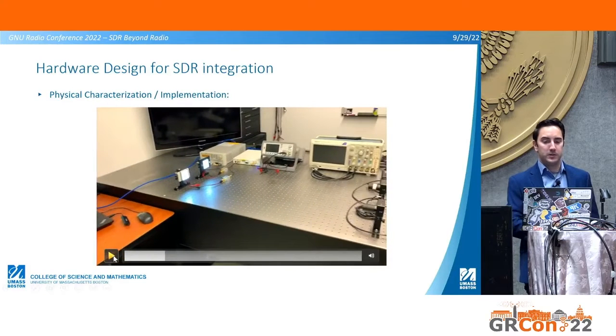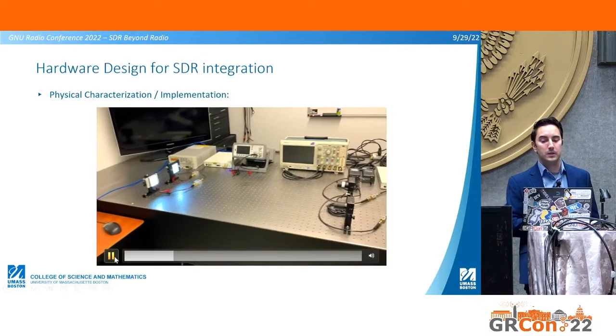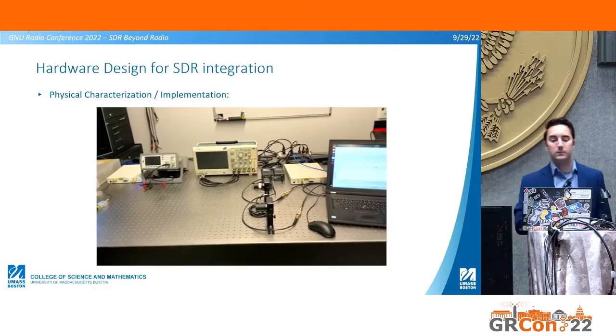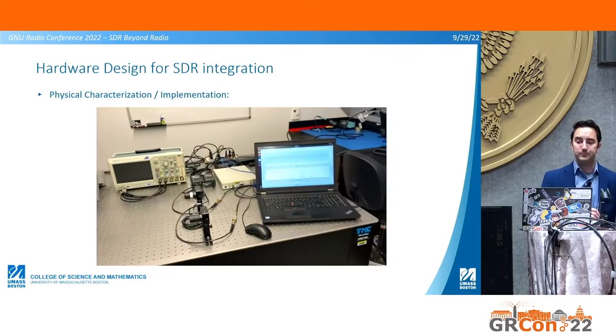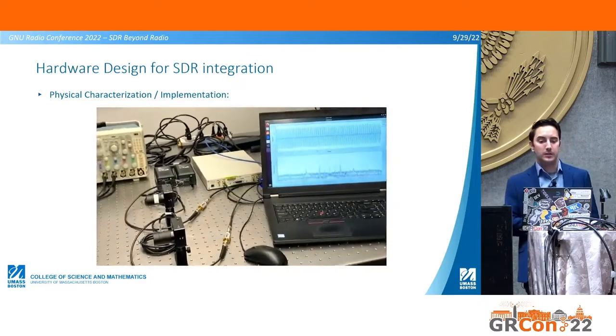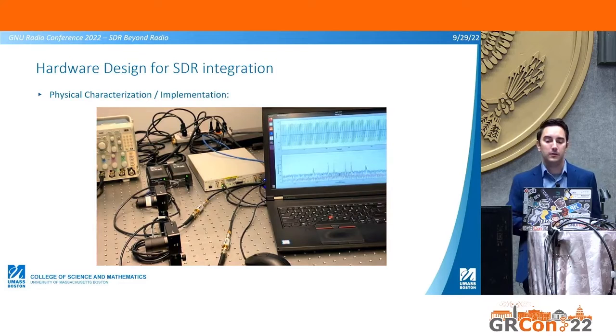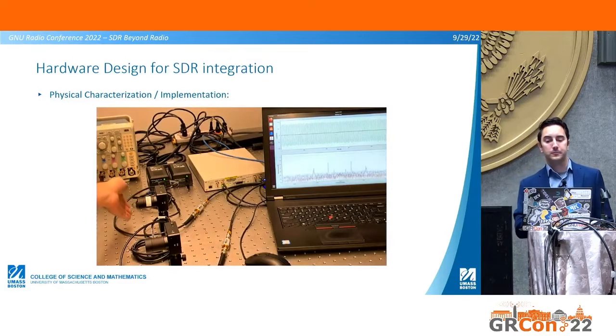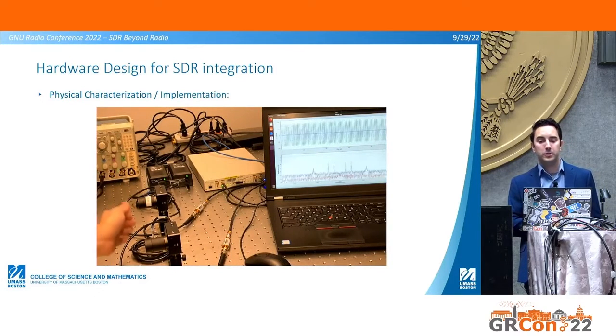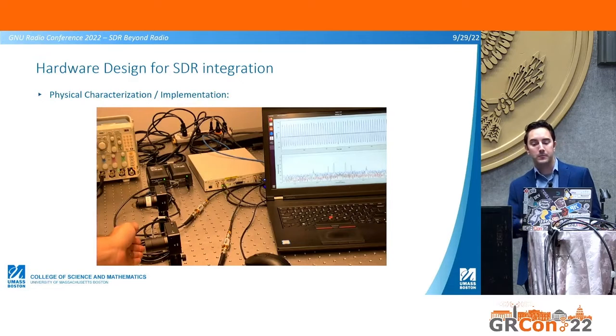So on the transmit side here, we have the USRP passing through two DC bias Ts, RF bias Ts, to bias your signal into the linear range of the LEDs. Both of these little low-cost LED arrays are right now just sending a sinusoidal signal, picked up at the two photosensors at the other end. As we zoom in, you notice that if we block either one of the channels, one channel goes away, and then the other channel goes away.